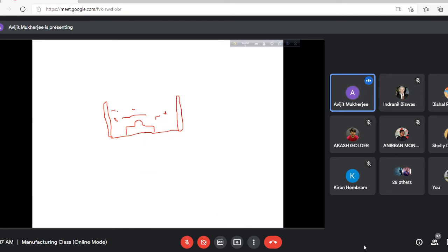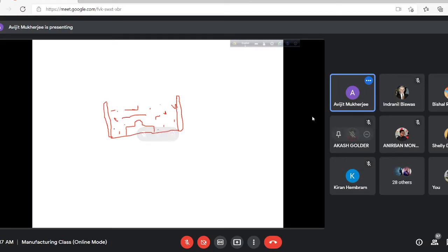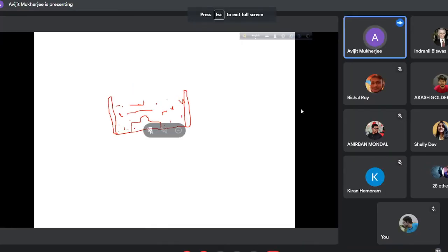What is the molding material? Clay-free dry silica sand, 75 GFN, mixed with 1.5 to 6% liquid-based sodium silicate or water glass. It is packed properly using a rammer or similar tool.